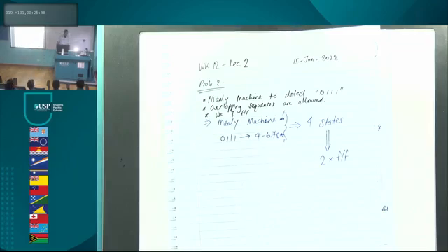Generally, in sequence detectors, you can ignore unused states and it won't affect the problem. In sequence generators, we have to route our unused states to a particular state. In sequence detectors, because the input is being fed in, you can ignore the unused states. Anyway, let's come back to this question.